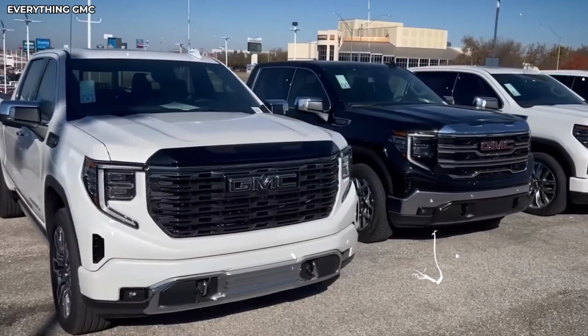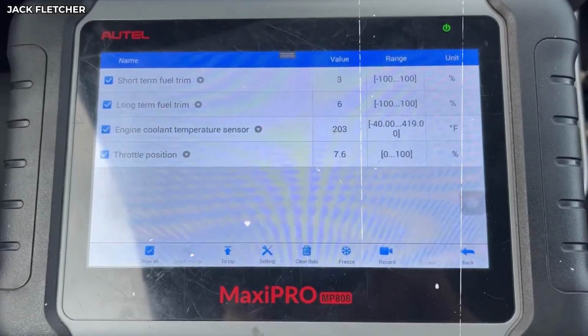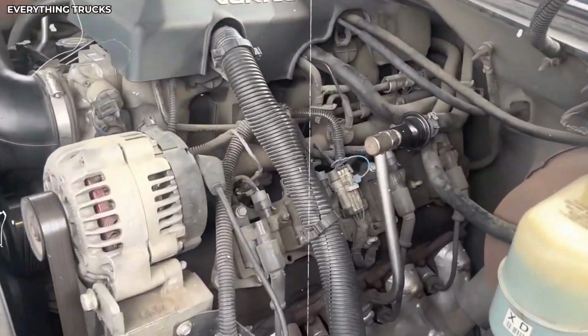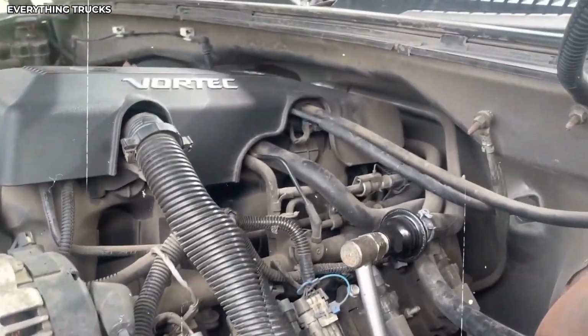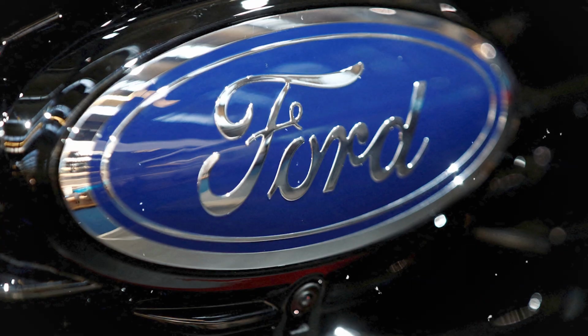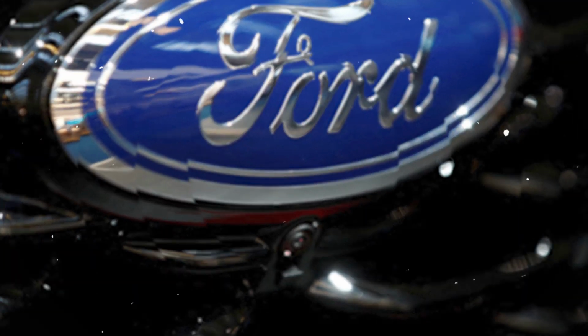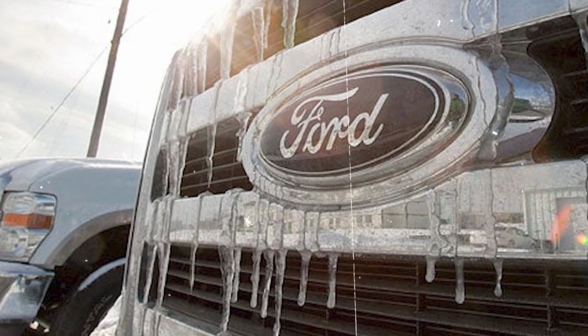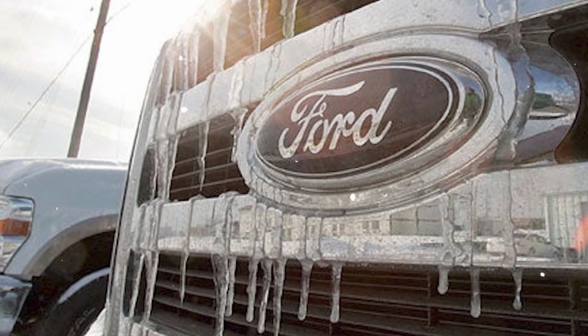Third, certain Ford models have known issues with adaptive learning resets. Some early 10-speed transmissions in F-150s from 2017 to 2019 can develop harsh shift quality or hunting behavior after aggressive resets. If you have one of these transmissions and notice problems after reset, a dealership may need to perform a transmission adaptive learning update using factory diagnostic tools.